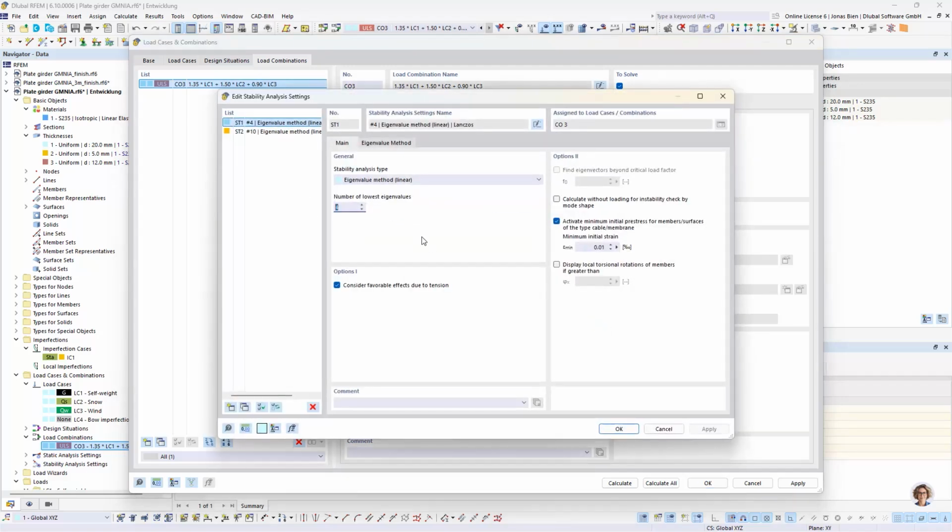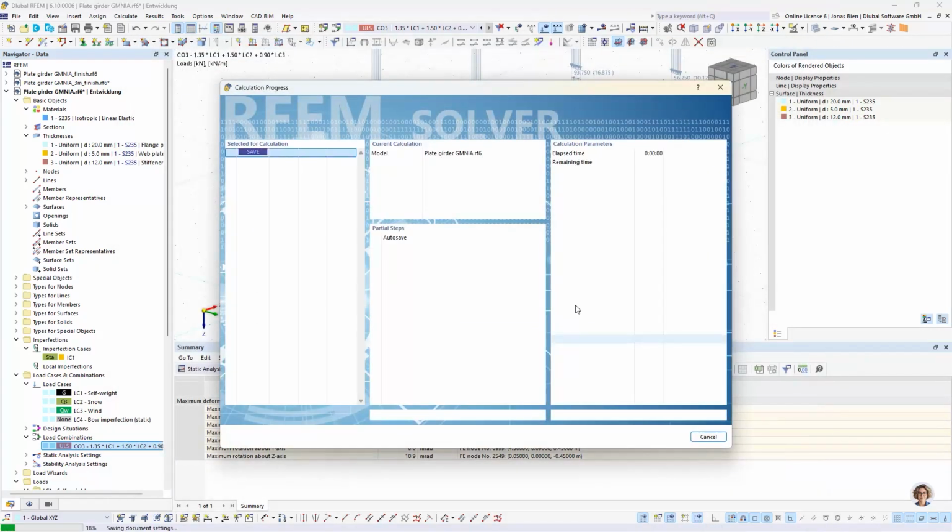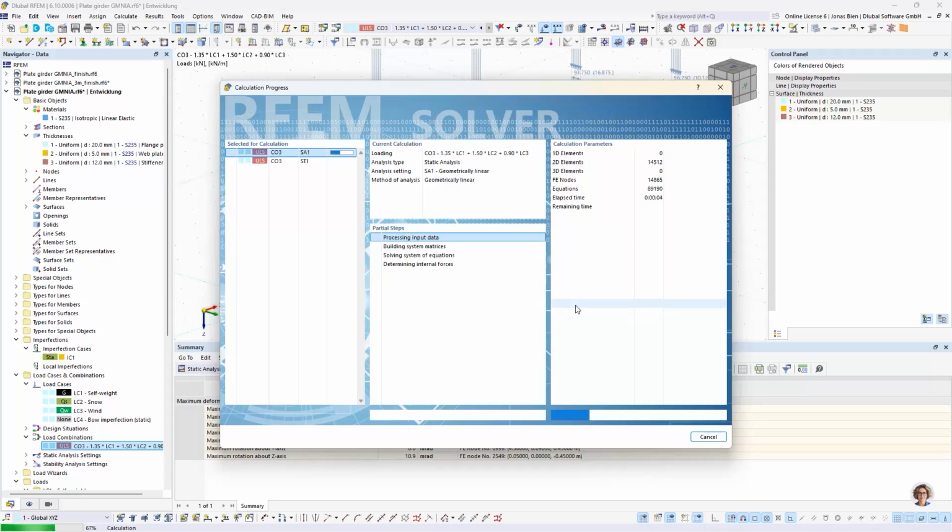The number of eigenshapes is maybe a bit low. I want to have some additional information, so I just set this value up to 20. So it will now, after defining the stress state in my structure, calculate the linear bifurcation factors, assuming everything is perfectly linear. So my whole problem is linear, and besides the linear bifurcation factors, I will also receive my respective mode shapes.